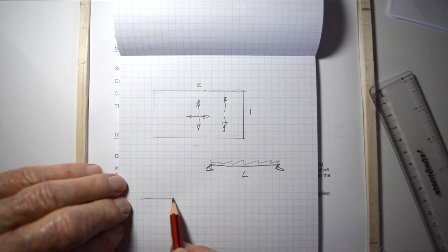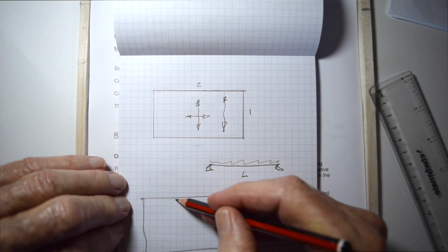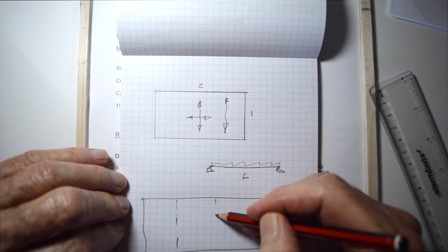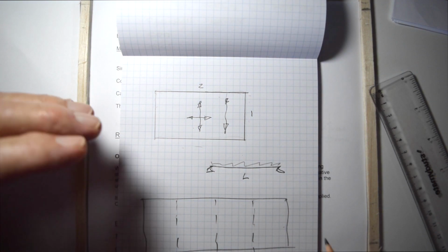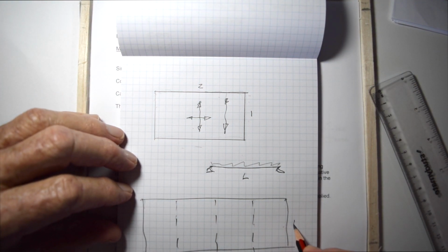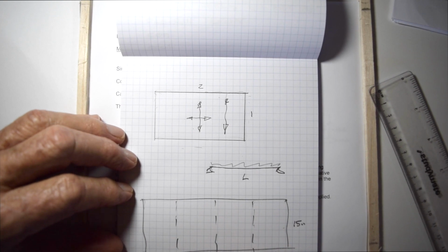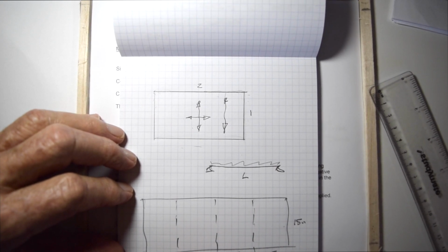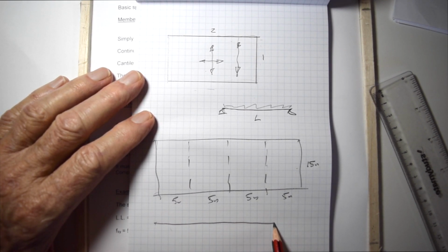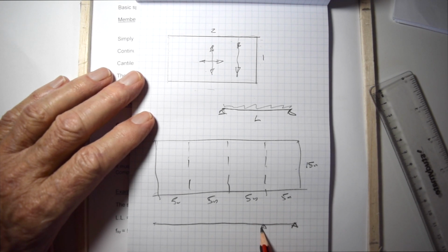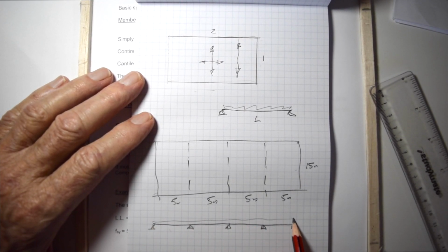So if you had a multiplicity of slabs, as we're going to be looking at in our tutorial, all spanning onto beams, these dotted lines are the beams underneath, there the ends are, and supposing this was 15 meters, and each one of these was 5 meters, each span between the beams, 5 meters, 5 meters, we would say that the actual, looking at a side elevation of it and drawing the idealized diagram, there our supports are, which are the beams, 5 meters apart with uniformly distributed load on.